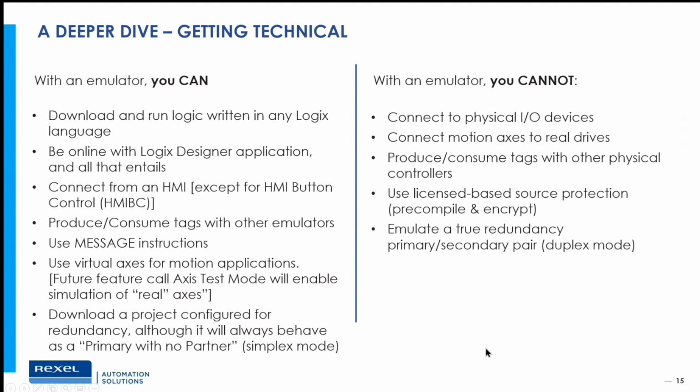Okay, getting into a little deeper dive here, just explaining a little more what you can do and what you can't do. I'm going to start over here on the you cannot. So you cannot connect to physical I/O devices, or connect to real drives, or produce/consume tags with other physical controllers, and that's a theme. Logix Echo will not control external physical devices. So that's something to keep in mind. Where that's going to come into play is that API that I touched on earlier with a simulator, and we're going to get to that, I swear.